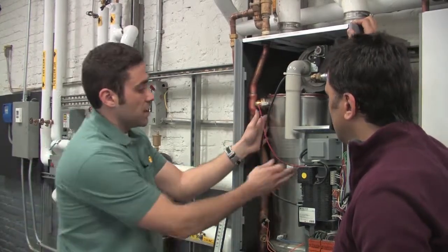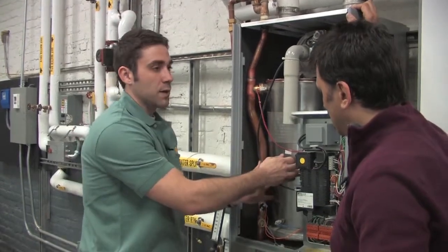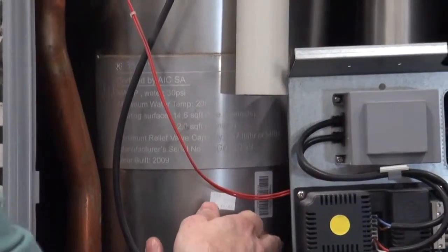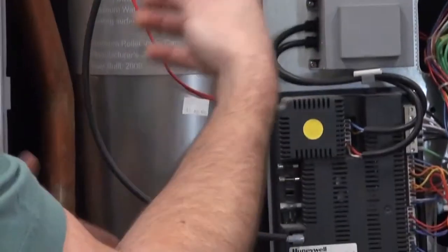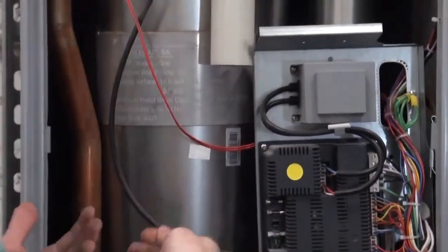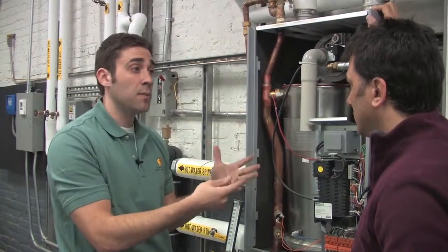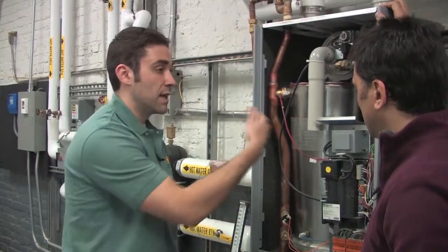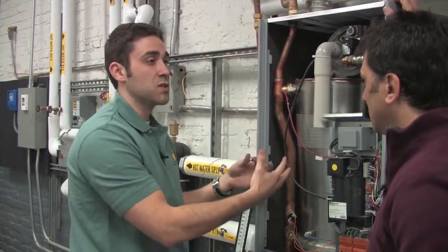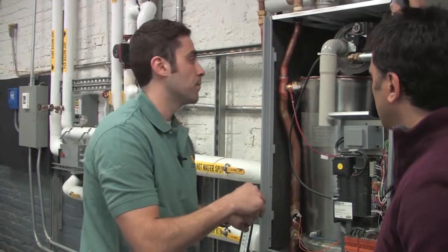Inside the heat exchanger here, we have about 2 gallons of water. It's a very small amount of water in this heat exchanger. So we need to continuously pump water through it to make sure that we don't overheat it. So with these types of systems, primary-secondary piping becomes very, very important. Having that water flow going through will keep our heat exchanger cool, making it work a lot better.